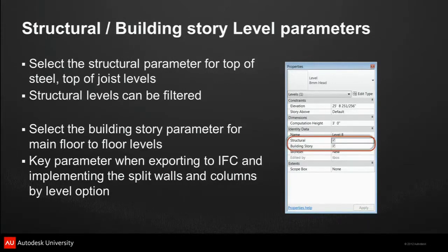Structural levels, building story levels. Did everyone see this when it came out? Structural levels, I was really excited about this. I thought that was cool. But it doesn't do what I thought it was going to do. My first thought is structural levels, I can make top of steel, top of joist, top of everything, and I can filter it out. That's terrific. I just assumed the architect wouldn't be able to see it if I called it a structural level. That's not how it works.